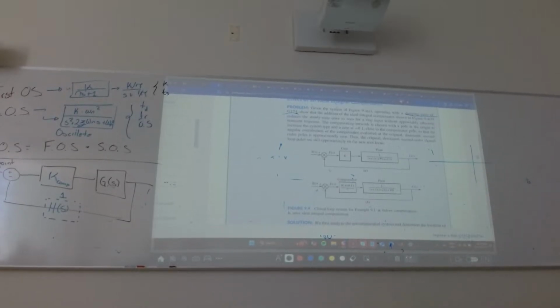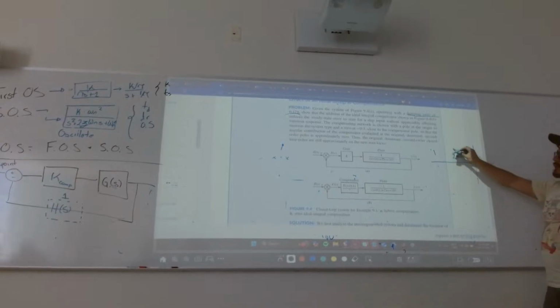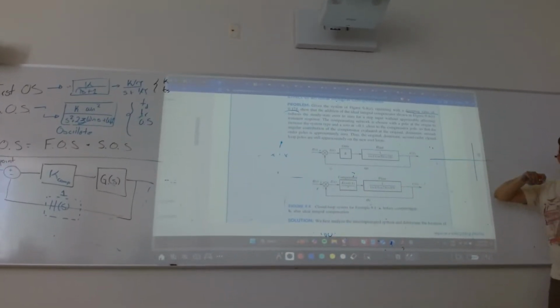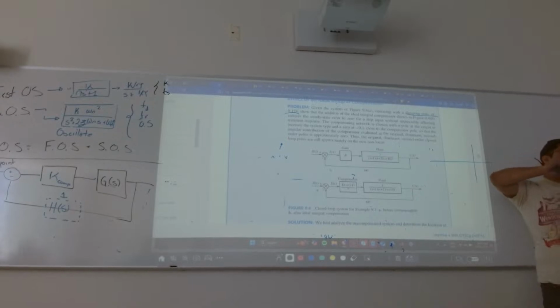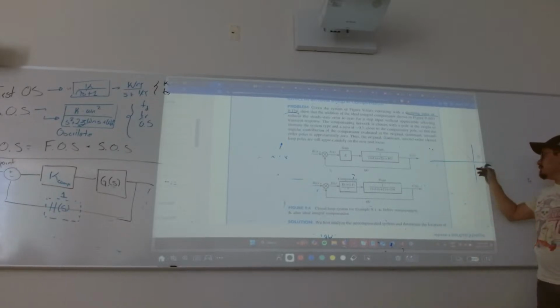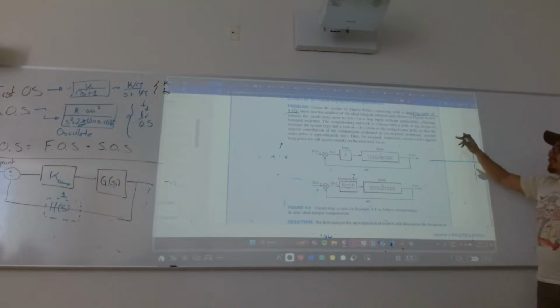If I were to do the root locus on this, there are two ways I can understand what is going on. The first one is plotting the root locus. A little piece of theory says that values that share the same damping factor are located along a straight line through zero. Everything in this line shares the same damping factor. What's this angle so that the damping ratio is 0.174?